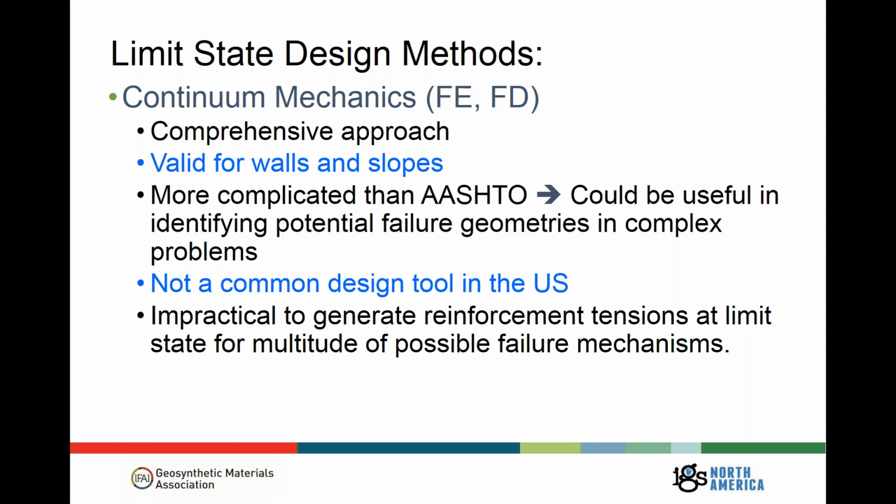So for those reasons, it's not a common design tool in the US. It's certainly being increasingly used for design. However, there's still a lot of uncertainty that surrounds some of those parameters that we have not pinpointed so well. Also, by virtue of capturing this critical failure mechanism, that's very useful. However, it doesn't give us a holistic, broad view on the reinforcement tensions at the strength limit state conditions for a multitude of possible failure mechanisms. We capture one, but what about all the other possible failures?